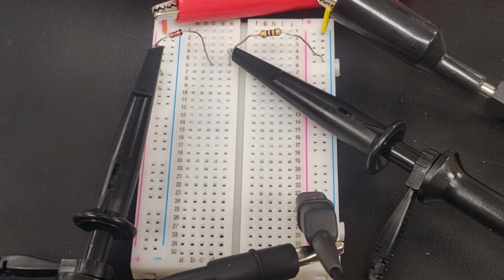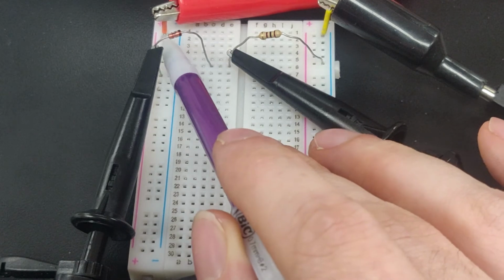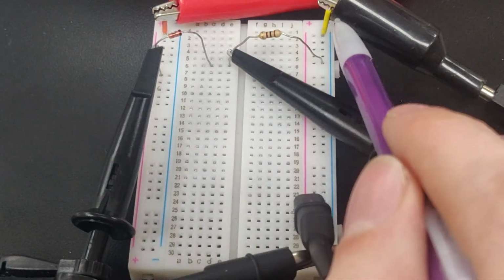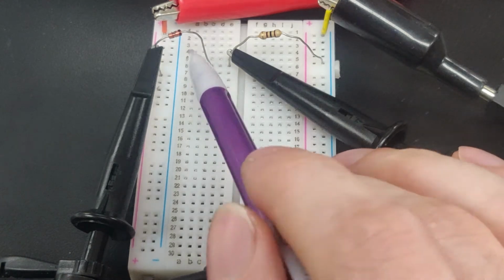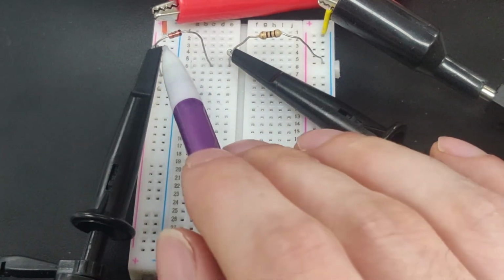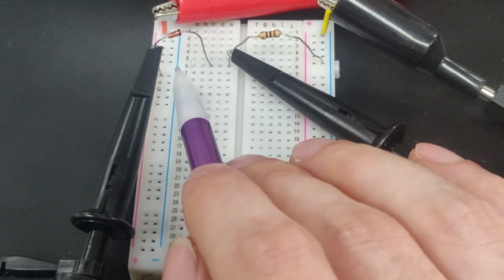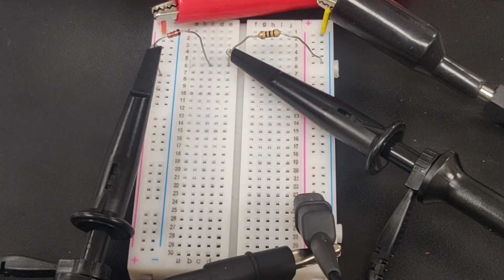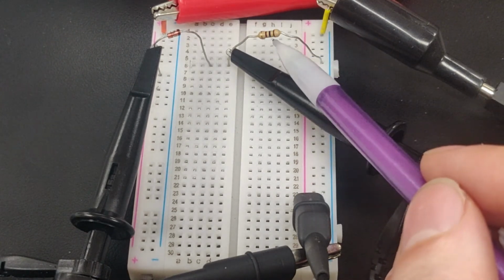Okay, so this first one actually looks quite similar to what we were just building with the forward and reverse bias measurements, where we have our current coming in from our function generator in this case, going through our diode, going through a resistor, and leaving. This resistor is a regular signal resistor, and the diode is a regular signal diode. For the rest of the circuits, we're going to be using the signal diodes. The Zener diode will show up in later experiments, where we'll use its functionality for different circuits. But for the rest of this lab, we're only going to be using the signal diodes. And this right here is just a 100 ohm resistor. So brown, black, brown. Okay.